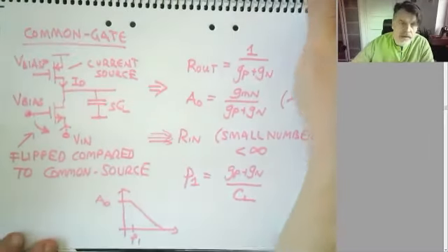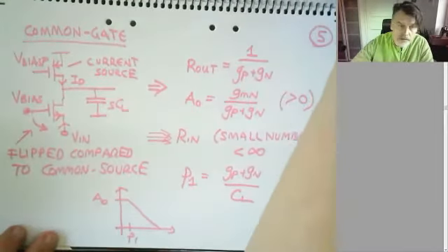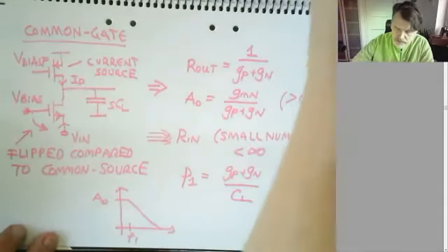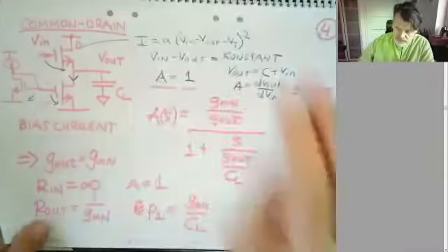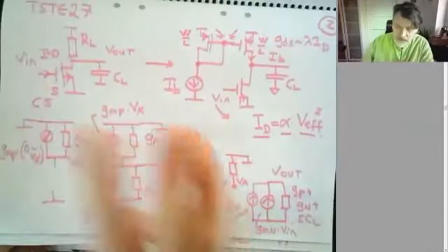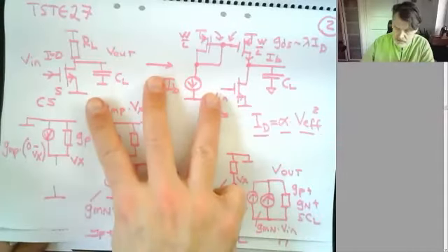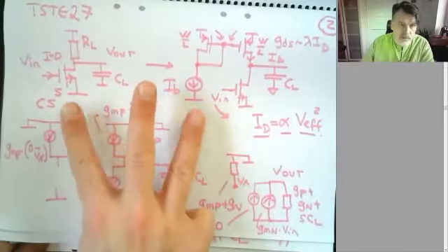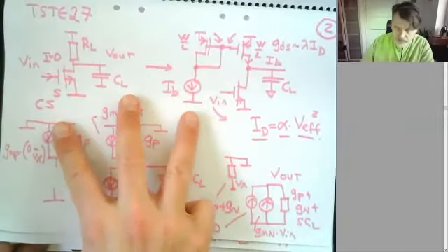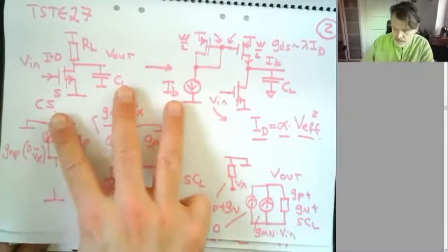So a quick guide through all the different building blocks that you have available as amplifier stages. These are three different ways to connect your transistor. If you think about it, the transistor has three terminals. So I can relate my input voltage, or the variance of my effective voltage on the transistor, in three different ways.